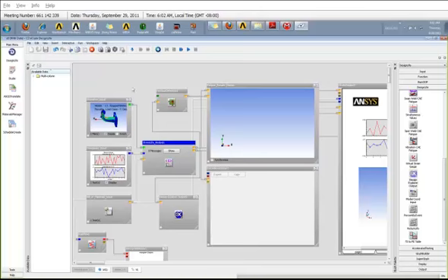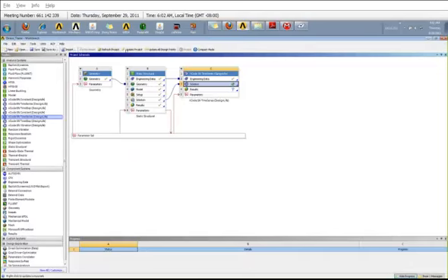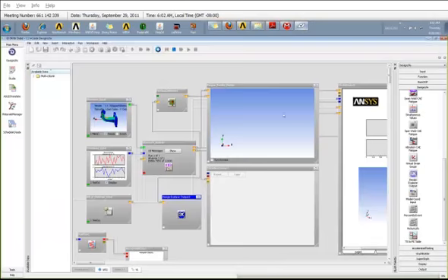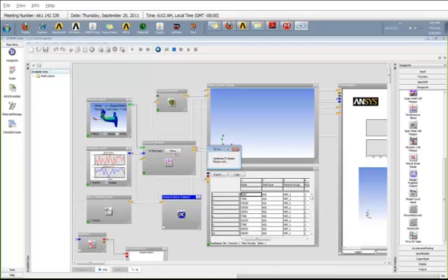So now pretty much I'm done. I have my simulation input, time series input. I have set my input and output parameters that I want to look at. I can hit this play button over here to run the simulation, or I can actually go into the project page and hit update project over here. That will also solve my nCode DesignLife. So you can look at the progress either in this progress toolbar, or I can just go to the nCode DesignLife and look at the progress bar. When it has a red button over here, that means it is solving or computing in that particular clip.